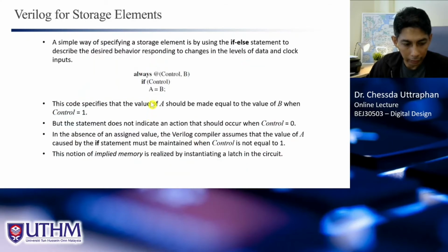But now, how do we want to create the storage element or latch in Verilog? Last time when we did the coding for a combinational circuit and used an if statement, I said that you need to have the else statement.